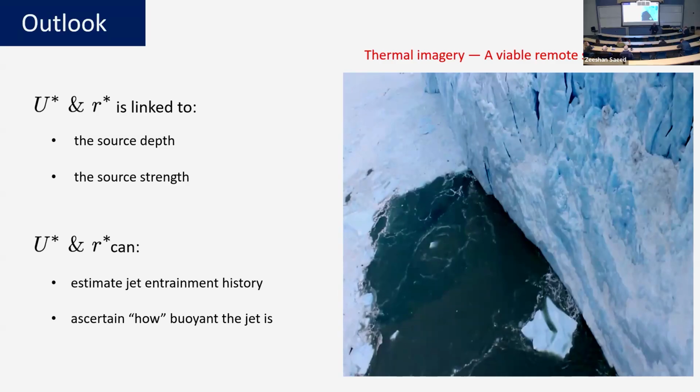And in the context of fluid mechanics, doing traditional velocimetry on free surfaces can be really challenging because you're relying on a laser sheet, and that's essentially a straight sheet. But the free surface won't really care about it. It will jump up and down, and it will create multiple problems like refractive index matching and total internal reflection. That's going to corrupt the data to a certain extent. So thermal imagery is really good in that sense: it's a non-intrusive technique that looks at the free surface and gives you a good estimate.